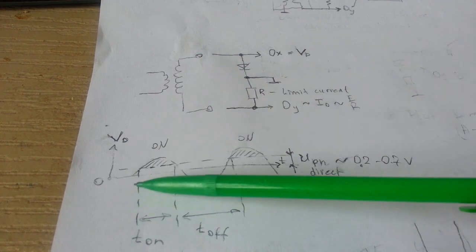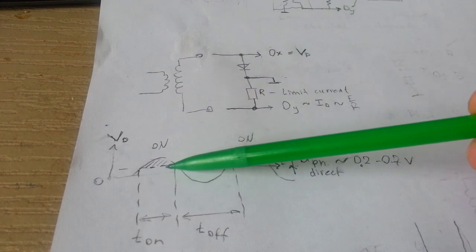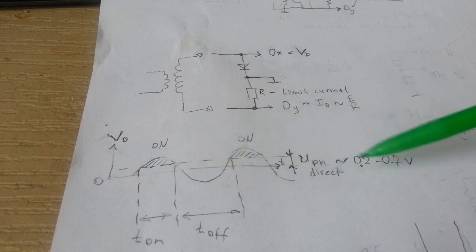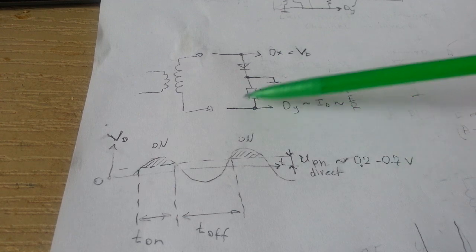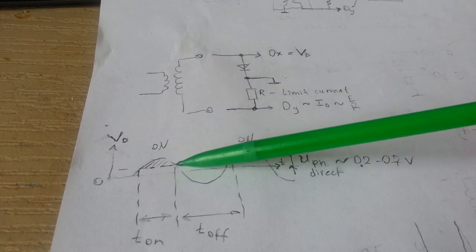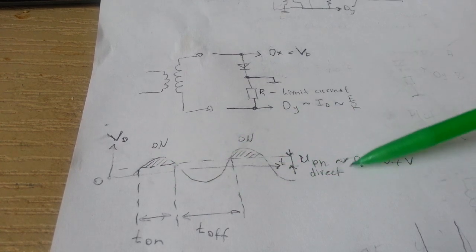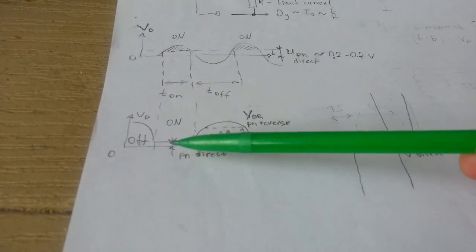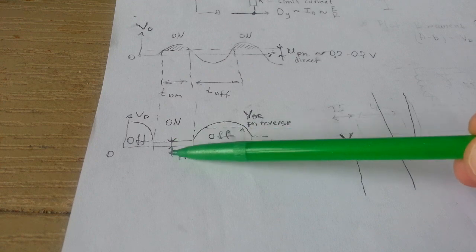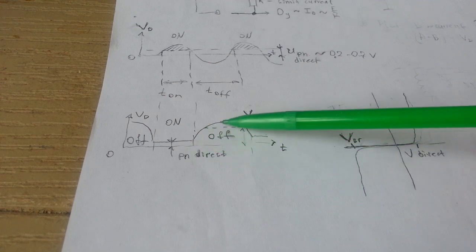So basically, if I have the sine wave at the output, I know that the diode is switched on when I cross the critical voltage, approximately 0.2 to 0.7 volts, depending on the type of the diode. Once this diode is on, the voltage drop across this diode is very small, approximately 0.2 to 0.7 volts. So on the graph, I'm going to see a flat line, a very small voltage, almost unnoticeable with regard to the other voltages.